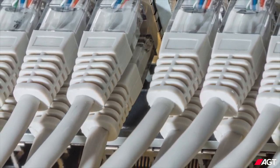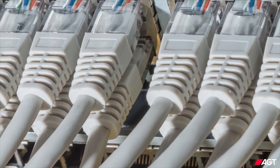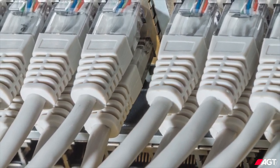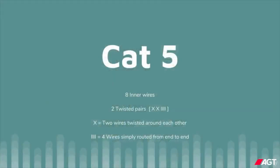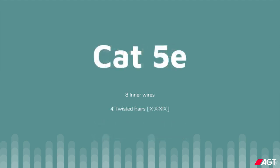So, in order to appreciate Cat7, let me quickly go over the previous categories and show you how they've improved. So, the Category 5 cable has 8 inner wires, but it has 2 twisted pairs inside. The twisting method is what helps keep out interference. Now we look at the Category 5e. It's got the same 8 inner wires with all wires twisted, so we have 4 pairs of twisted wires. This reduces interference and crosstalk even more.